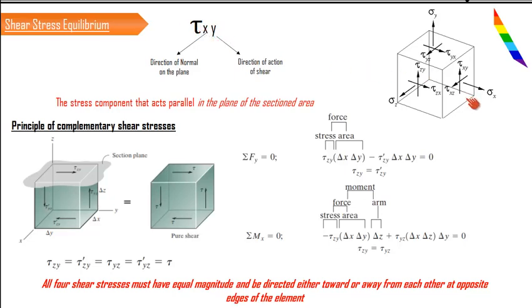If you look at this plane, we can see that tau x and this shear is acting in the z direction. Similarly, this shear is acting on a plane which has a normal in the x direction and it is acting in the y direction. So it is named tau xy. This is how you have to read or understand the stresses.